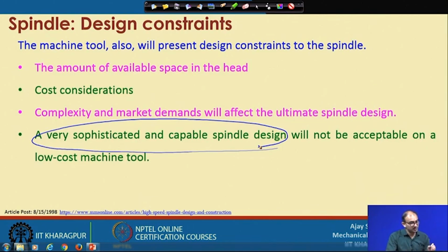But suppose your machine is a routinely used CNC machine, and you want to go with a very high air bearing and extremely high lakhs of RPM, then your machine tool is actually not suitable for that type of spindle. First, you have to find out whether your machine is capable in terms of stiffness, damping of vibration, and axis orthogonality, that means the x, y, z axes should be exactly perpendicular to each other, which we have seen in geometric error.